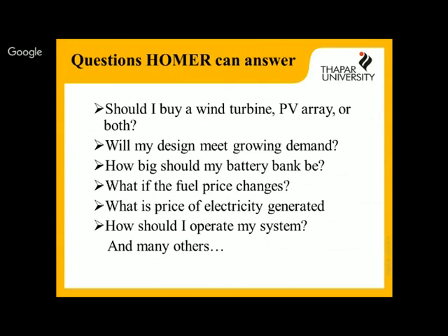So what will happen if I want to meet all the demand? I need to have a storage system. Suppose there is no sun continuously for 10 days, let's say as one example. That means I need to have a capacity bank of 10 days if I'm using the standalone system.